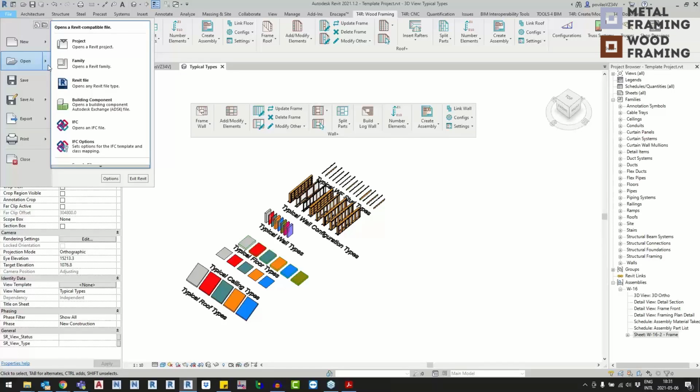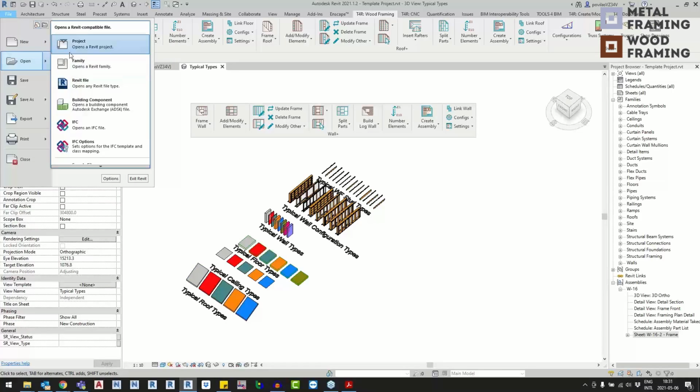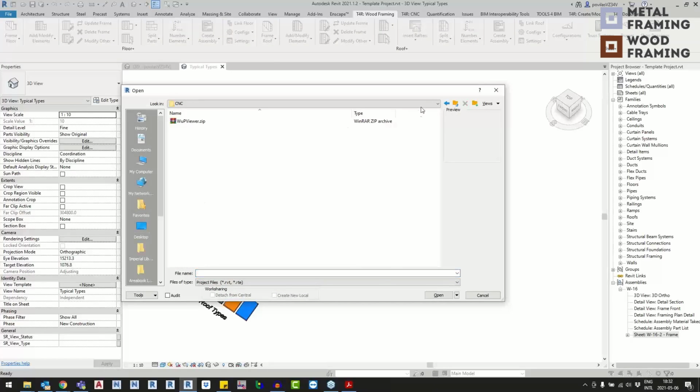Before we move on to families, we have this Revit template file. That's a Revit template RTE extension file that could also be a base point for your new project. Whereas a template project is where you keep your types of elements and your configurations worked out. You have your elements laid out, and you can change the sizes of those elements. You have view templates and all other kinds of settings.